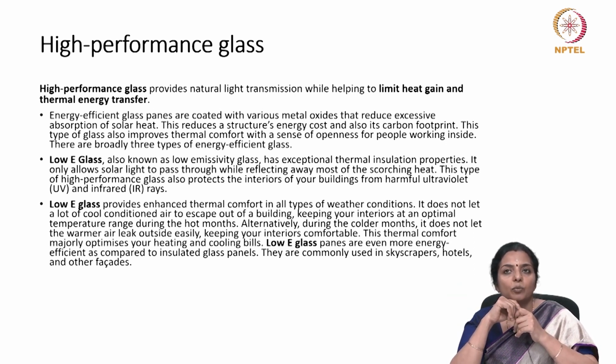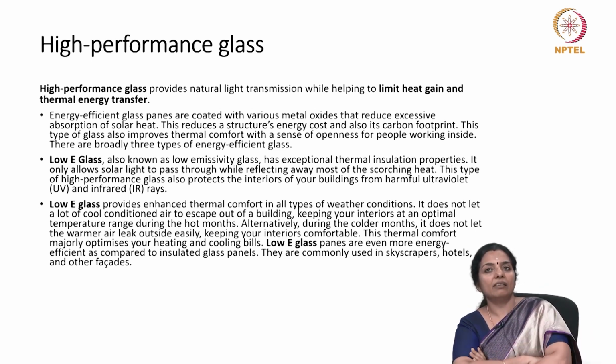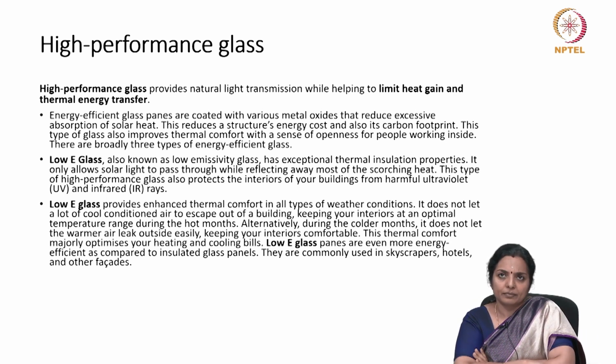High performance glass provides natural light transmission while helping to limit heat gain and thermal energy transfer. Energy efficient glass panes are coated with various metal oxides that reduce excessive absorption of solar heat. This reduces a structure's energy cost and also its carbon footprint. This type of glass also improves thermal comfort with a sense of openness for people working inside. So, there are broad classifications of this glass.